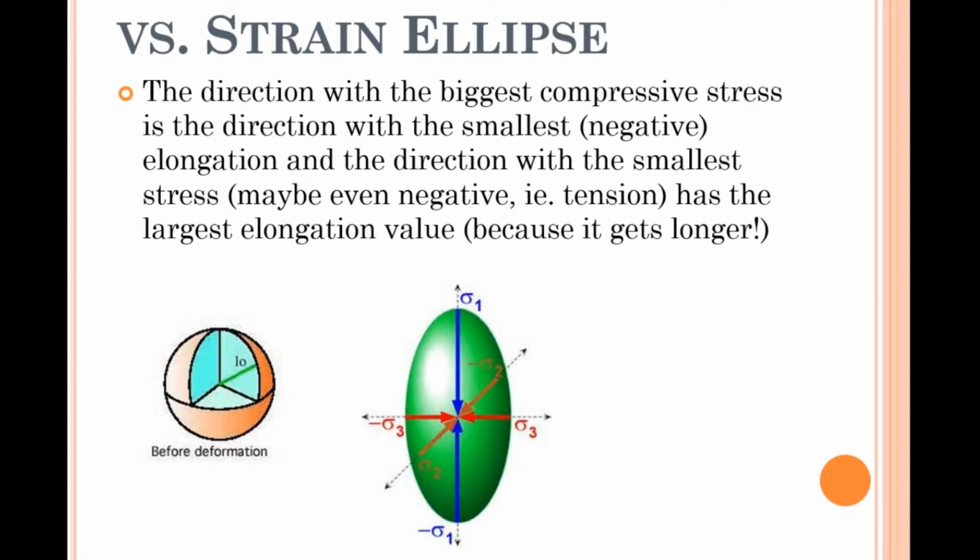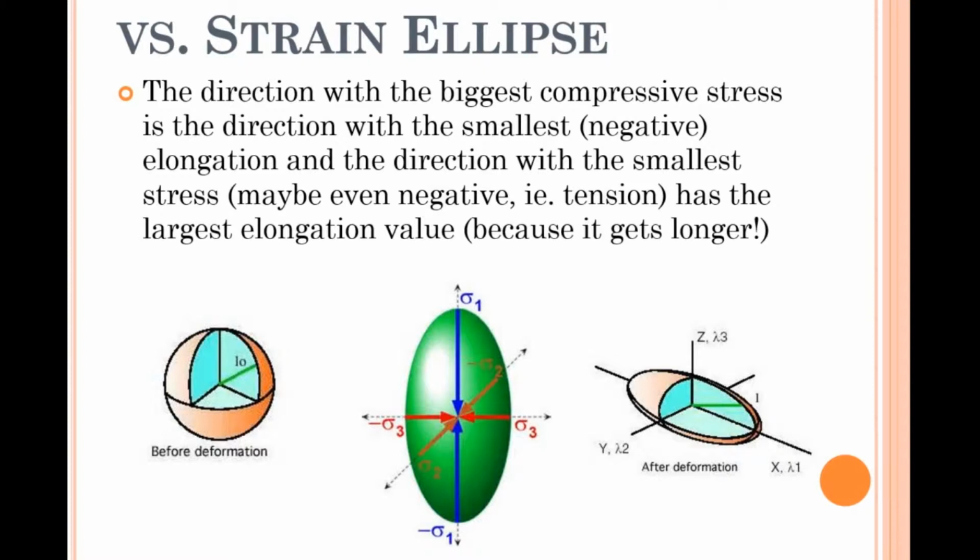So this particular stress ellipse on the sphere is going to make it look like this. It's squished very much vertically, and it bulged to the sides more in the sigma 3 direction, left and right, than it did front and back in the sigma 2 direction, because sigma 3 was the lowest stress. So the ellipses both tell you greatest and lowest, but they're opposite orientation for the same circumstance.